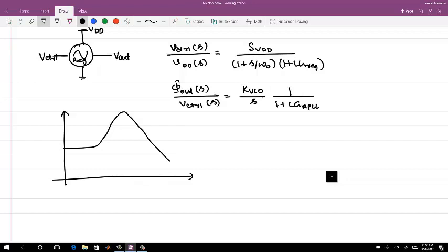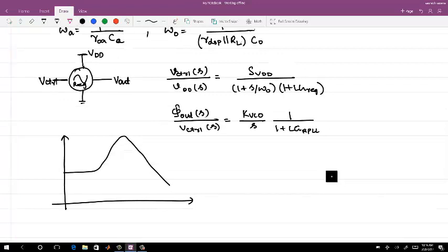So in case of this, I am writing with the whole of this VCO in the PLL loop. Do not think that means you have all the phase detector feedback loop there. Let me just start with another color. There is some other block which is the PLL. I am writing the transfer function for the whole loop, not just for the VCO. So this is the transfer function for V control by VDD.